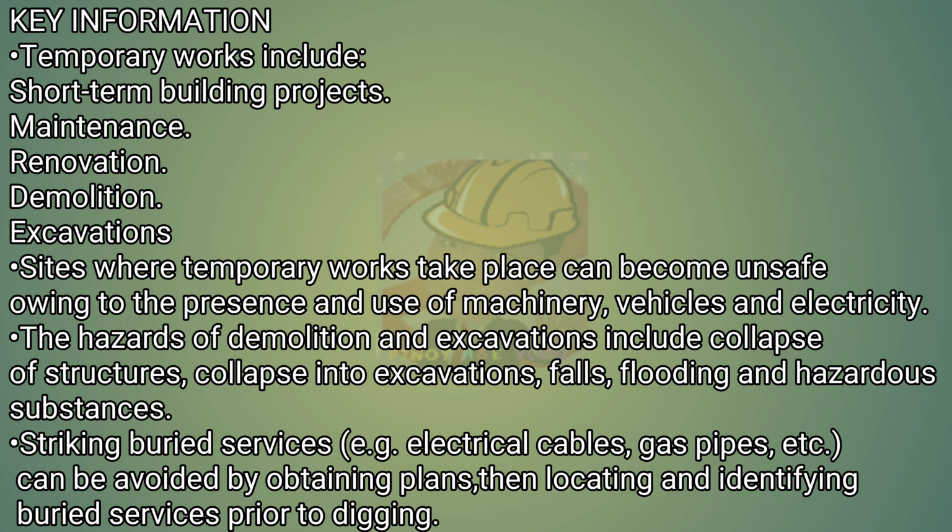Key information: temporary works include short-term building projects, maintenance, renovation, demolition, excavations. Sites where temporary works take place can become unsafe owing to the presence and use of machinery, vehicles and electricity. The hazards of demolition and excavations include collapse of structures, collapse into excavations, falls, flooding and hazardous substances. Striking buried services, for example electrical cables, gas pipes, etc., can be avoided by obtaining plans, then locating and identifying buried services prior to digging.